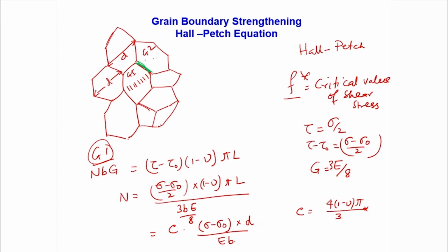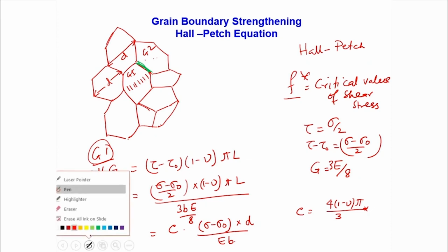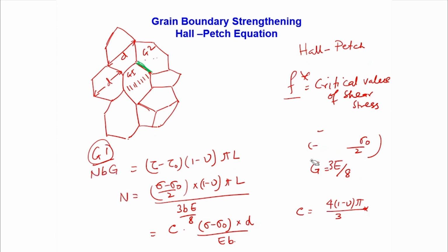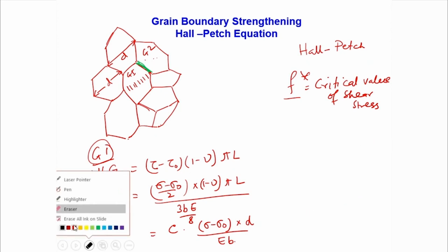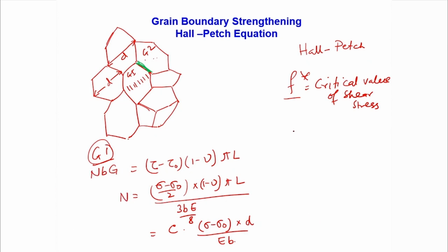Now, the force these dislocations exert on the obstacle is magnified by their number. So the obstacle can be overcome. When can the obstacle be overcome? Can you imagine? Well, the obstacle can be overcome at the time when N times (tau minus tau 0) multiplied by B must be greater than or equal to F star. Then only the obstacle can be overcome.